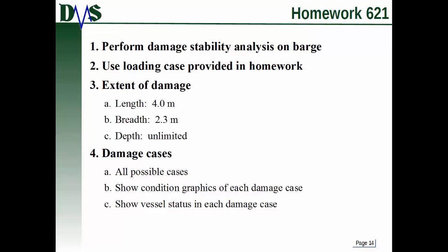Now, what damage cases do I want you to develop? I would like you to develop all the possible cases. Remember to take a look at symmetry. You only have to do both sides if it's not symmetric in that section. And then I want you to show the condition graphics for each damage case. That's really useful to be able to see what the damage actually looks like. And then show the vessel status for each damage case. That's going to show also the equalized status.